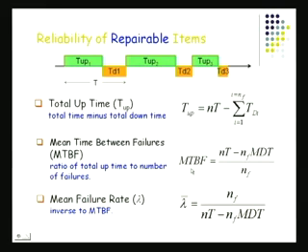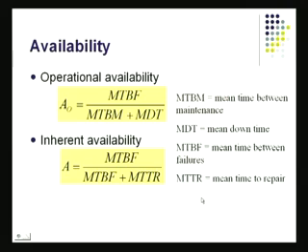Again, I've got mean time between failures. The formula is shown here. And the failure rate also is shown here. The mean failure rate is also shown here. These are metrics which are used quite often in doing reliability engineering. Then you've got something called availability, which is the period of time over which a product is available. And you can actually utilize this, and that is MTBF divided by MTBM. That is the mean time between maintenance plus the mean downtime. These together cover the total time.